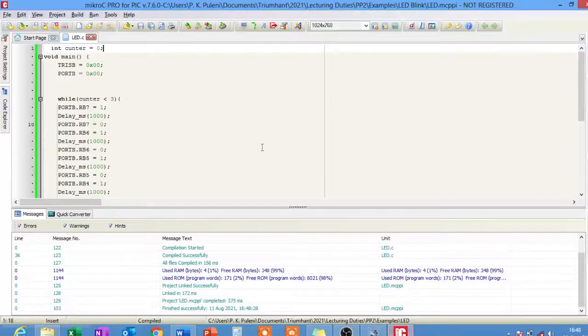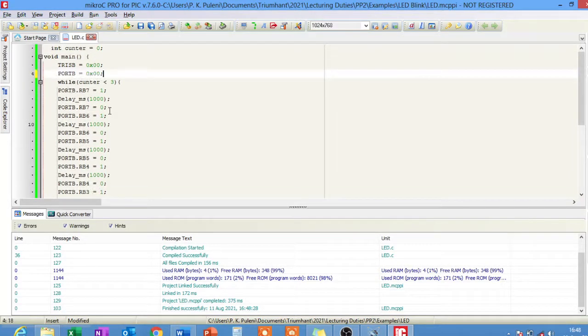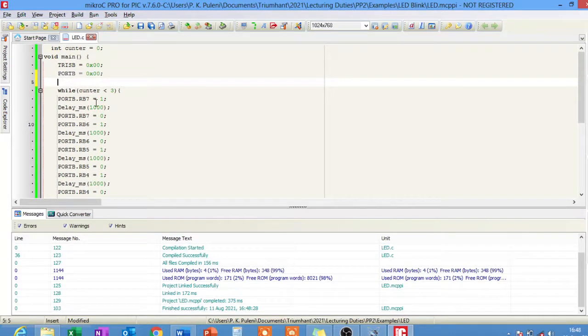All right, I think I had forgotten something here. In this microelectronic C, our variables are declared outside the main. So you don't declare them inside, but you declare them outside here. That's where we declare our counter. If you put it inside the main function, then you are going to get errors like I just did. So you declare your counter there and also initialize it to be 0 at the beginning.